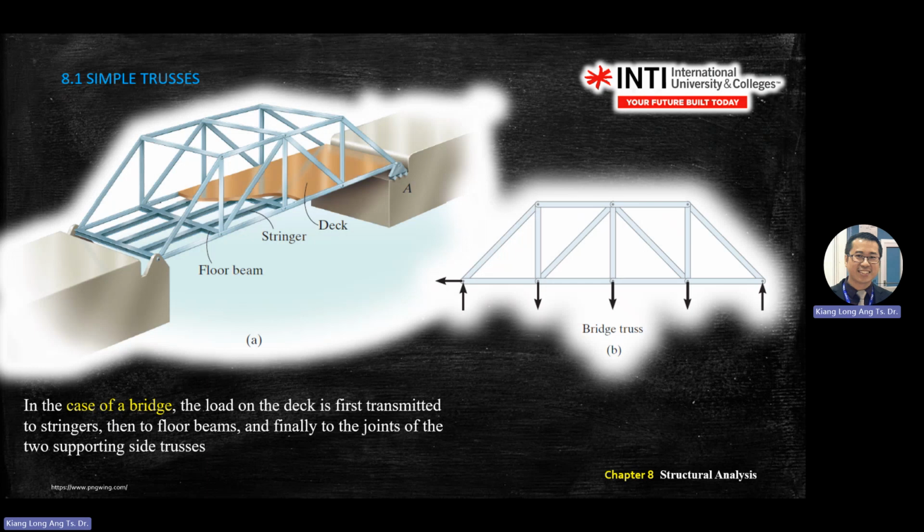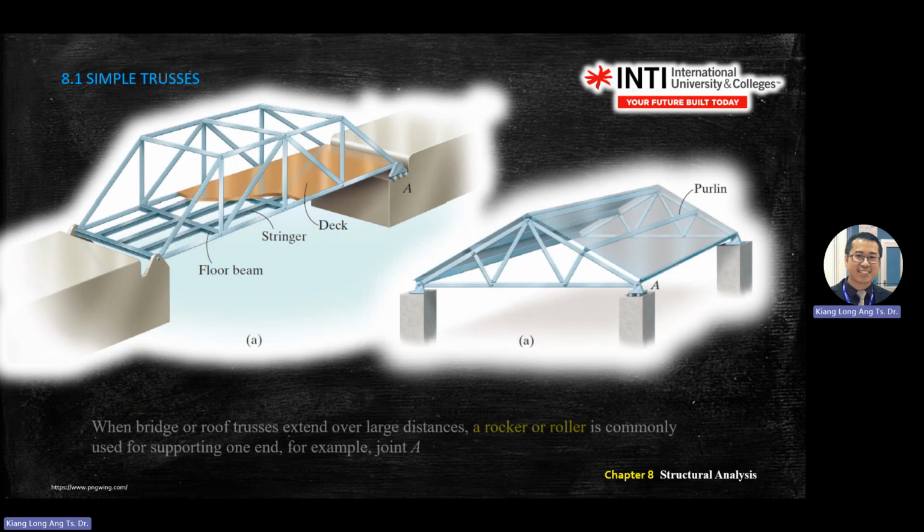So why is this one pointing up? You should already understand. This one, point A, is a roller connector. A roller connector only has one reaction. Then the rest here will be because of the weight from the body, so this one will pull down, pull down, pull down, and so on. This one is also the same, also a roller. This one is also a roller, but this one is a pin, and so on. This is just an application of what you learned in the previous chapter.